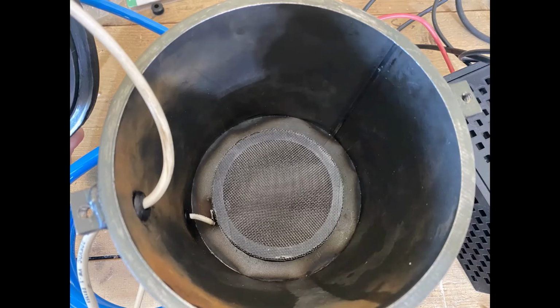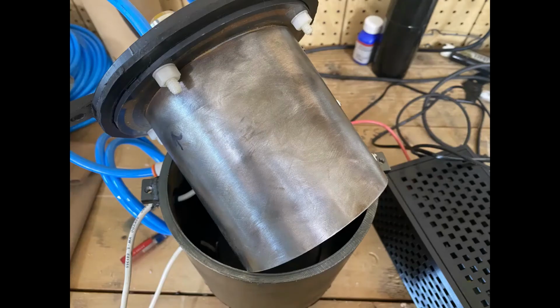Looking down into the tube, you see the lower ionizer as well as the inlets for both our negative and positive charging wires. Attached to the lid is the collector. One may notice how it is separated from the actual cap by a PVC disc. This helped with the safety of our device and acted as an insulator to absorb any electricity. The disc was secured to the cap by 4 nylon bolts. A rubber ring was also added around the edge to ensure an airtight seal inside when the upper and lower portions are put together.